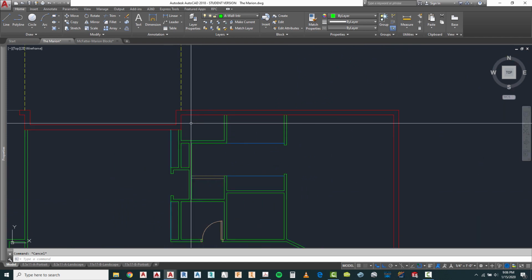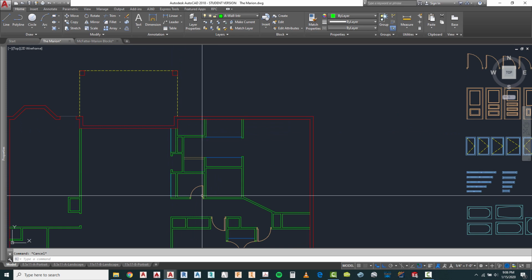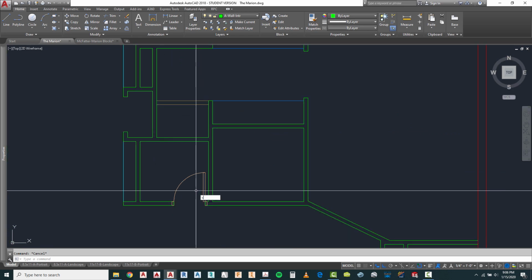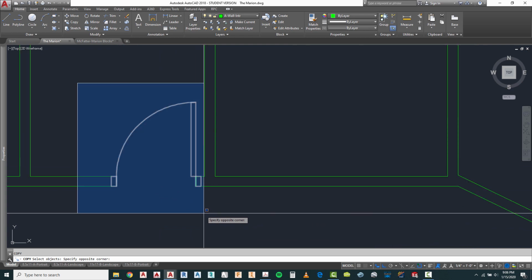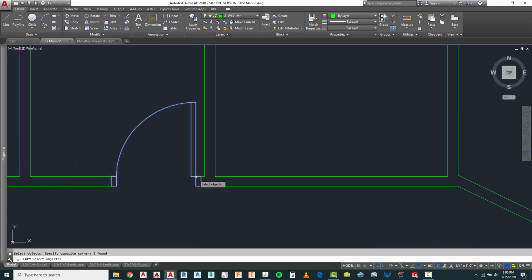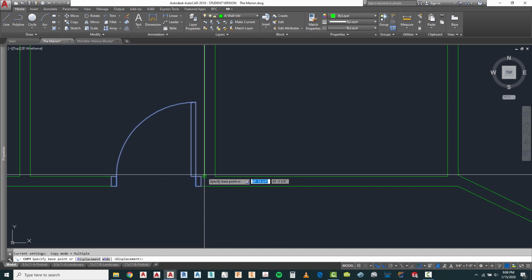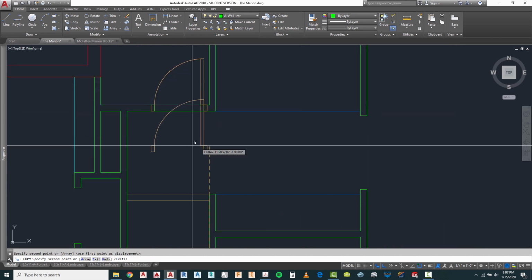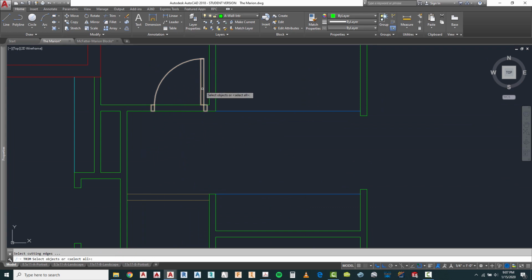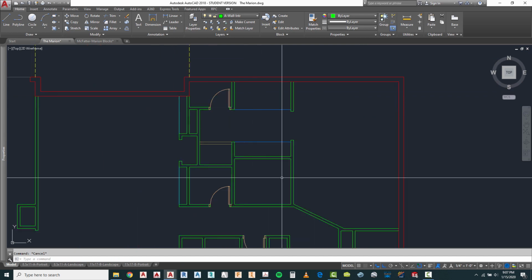We have a toilet enclosure right in here where we want to use a 2-6 door. So let's copy this, and I'm going to copy it together with those A-wall interior lines that we did in there, and I can bring this up to the same point right in here. Use my trim command, and I can get rid of these 2 lines that are located right there.